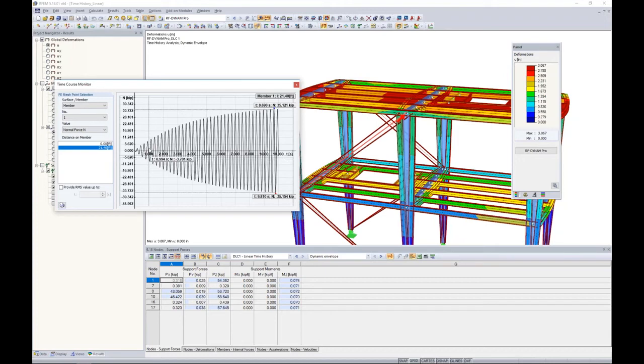We've already determined that, but this is a tension-only member. I certainly have tension forces here, but I also have compression forces. Well, this is a cable element. By no means can it take these compression forces, but this is a limitation of a linear analysis. That tension-only member was replaced with a truss member that can take both tension and compression.